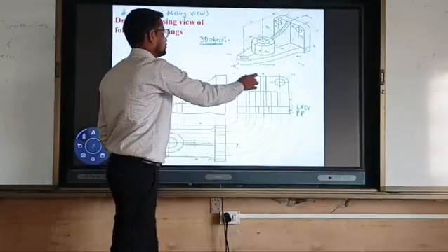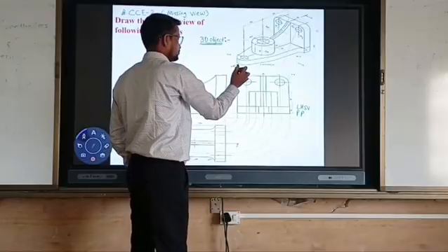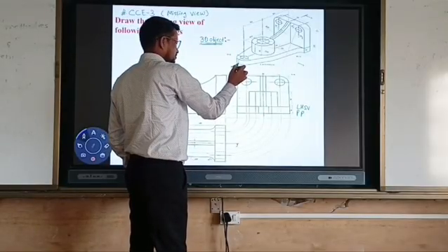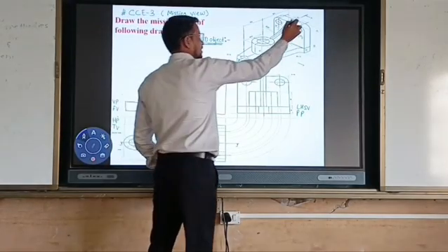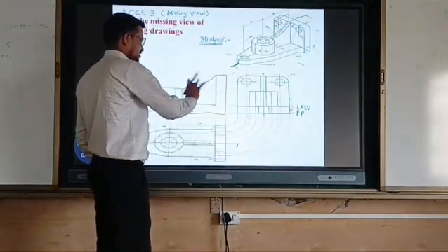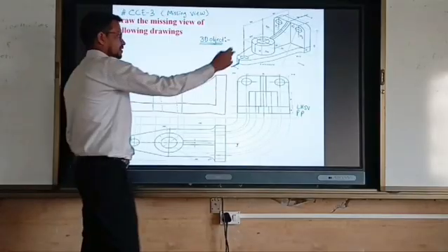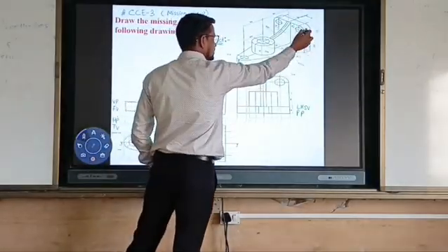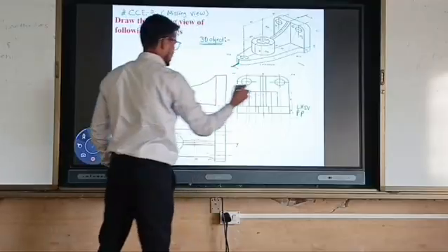Why? In the front view, they have strictly mentioned a sectional view. Now, from where I start cutting at this point to where I end at this point, half the portion is already removed, and on the rib there is no hatching line. But the base hatching line must be there, and for this rectangle the hatching line must be there.